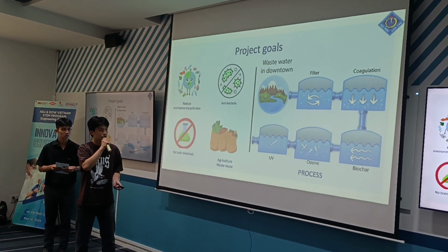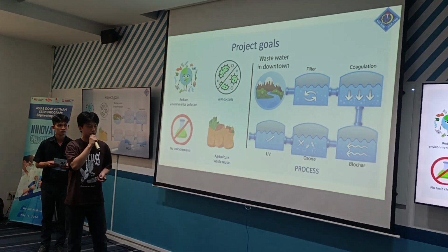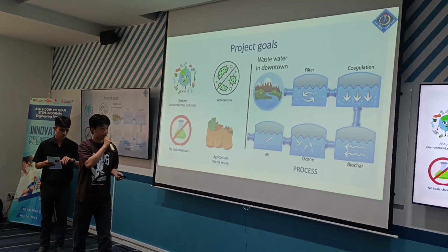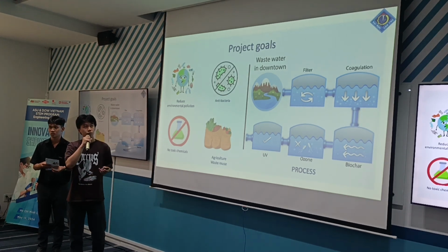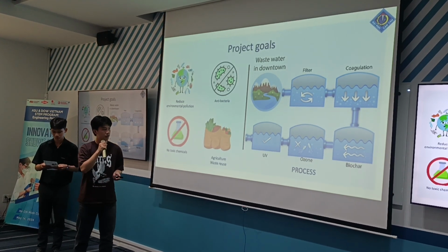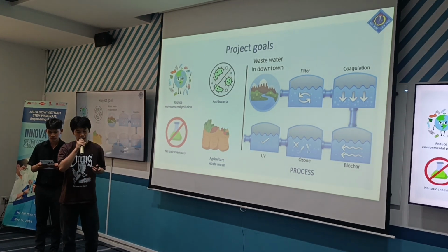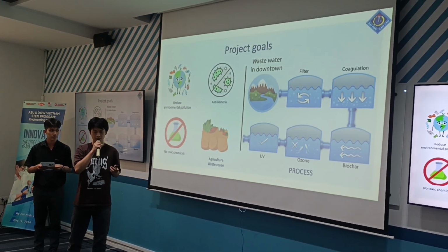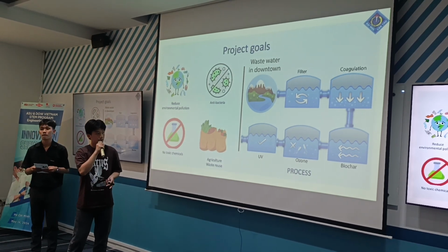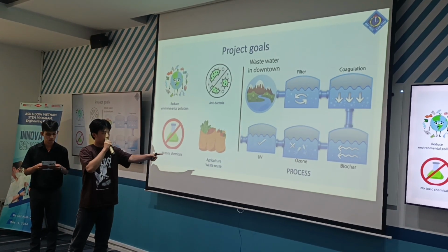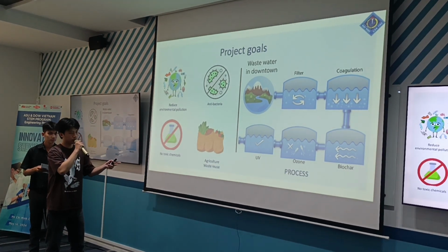And then the treated water will continue to the biochar, which we have 3 sections. The rocks will also be removed for the extra TSS, and the sand will remove the heavy metal. And finally, the biochar will remove the phosphorus and the ammoniac, which is the main components in wastewater. And finally, the ozone and the UV filtering, we will be putting together for support.